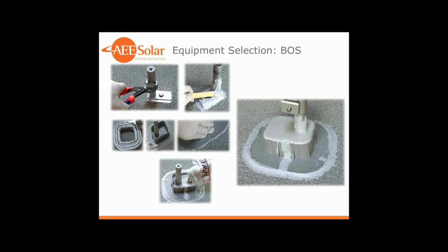So by putting the M1 sealant or adhesive on there first, that pourable fill will bond to that more aggressively, and as the array and pipe moves around over time, it will withstand it and maintain a proper seal. So this will be a very effective installation for years to come.